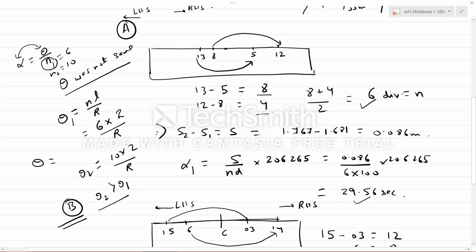This is just for understanding and going deeper into the question. You have already solved the question. In earlier questions with only one bubble tube, theta is the same when you move, but over here theta changes. The basic conclusion is that bubble tube B is more sensitive than bubble tube A, as the alpha value of bubble tube B is greater than that of bubble tube A.